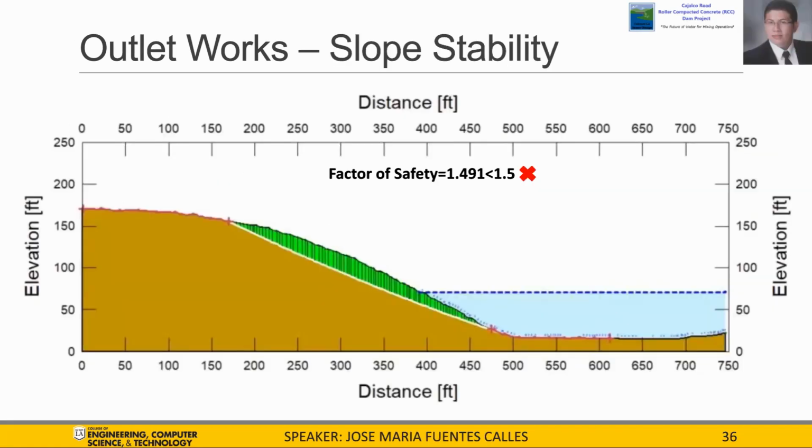A slope stability analysis of the existing ground surface at the incline intake structure location was conducted using GeoStudio's SlopeW software. In the absence of a geotechnical characterization at the site, the subsurface soil profile was assumed to be homogeneous, cohesionless soil with a unit weight of 120 pounds per cubic foot and a friction angle of 32 degrees. A static slope stability analysis was performed using Bishop's method.